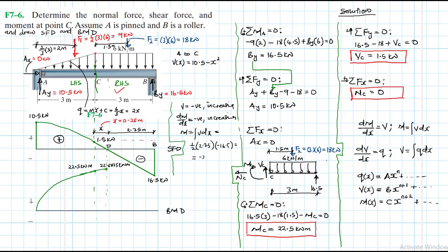So we have a negative 22.6875. From where we are coming from, we have a positive 22.6875. They will interact, so a positive 22.6875 plus a negative 22.6875 gives us 0, so that we close our moment diagram. The closure is vital again.